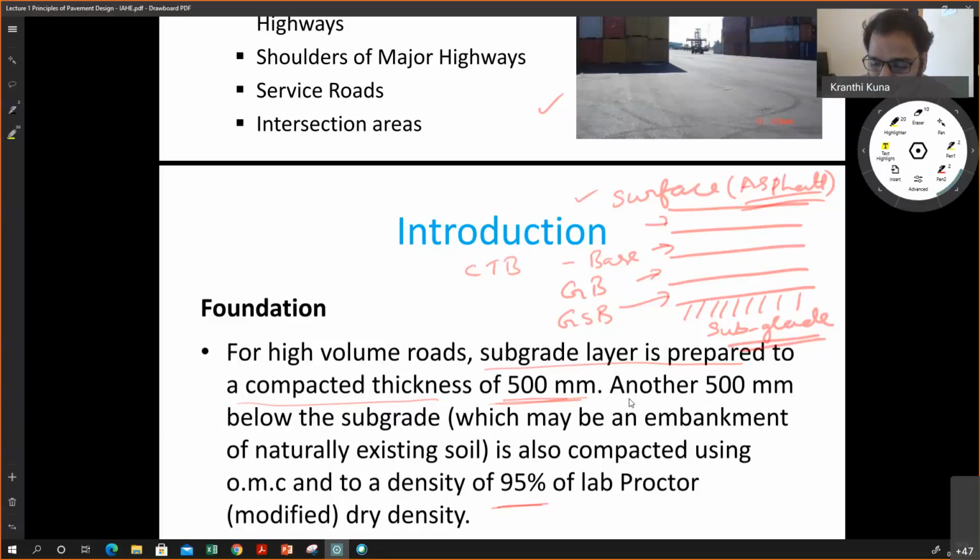The point I want to highlight here is that rigid doesn't mean that it is not flexible. For example, concrete pavement and bituminous flexible pavement can have the same deflection. If you are constructing very strong pavements, for example with a cement treated base and upon that very stiff asphalt, the deflections might still be very low, but we still call it a flexible pavement.